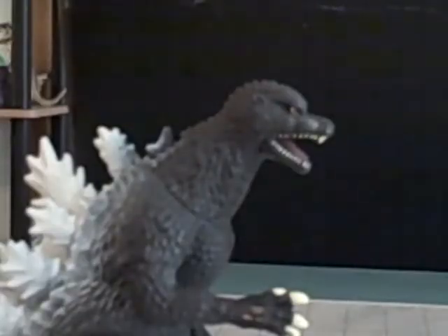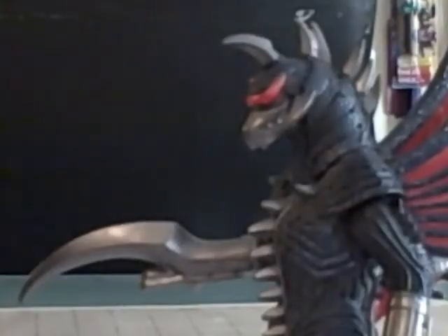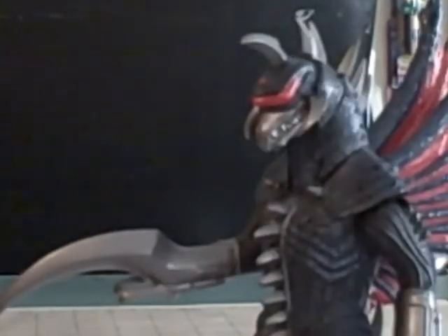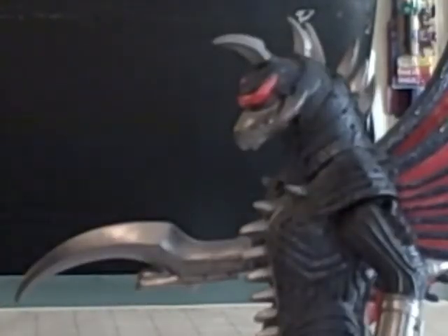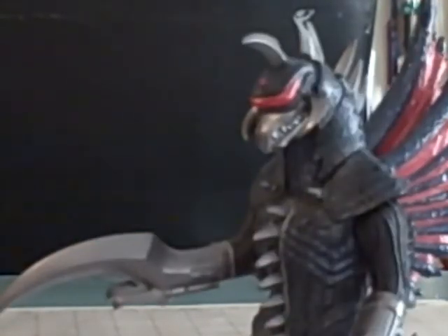What about the lever? Well, Godzilla, there are 3 types of levers: first, second, and third class. You see, the first class lever has its fulcrum between its effort and its load. The effort moves farther than the resistance. Some common examples of a first class lever are a crowbar or a seesaw. Now, a second class lever has the load between the fulcrum and the effort, so the effort moves farther than the resistance. An example of this would be a nutcracker or a bottle opener.